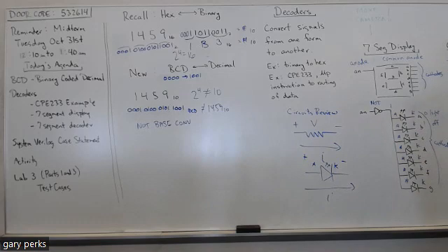And the other property of a transistor, besides acting like a switch, is that it can provide current gain. Now you're going to learn about how it does that when you take your first 300 level electronics class. But you see, the purpose of this NOT gate, which is just a transistor, is to provide some current gain so that these segments will light up bright. If that NOT gate wasn't there, the segments would still light, but they'd be pretty thin. So this inverter, which is just a transistor, provides some current gain, so we get brighter LEDs when they light.